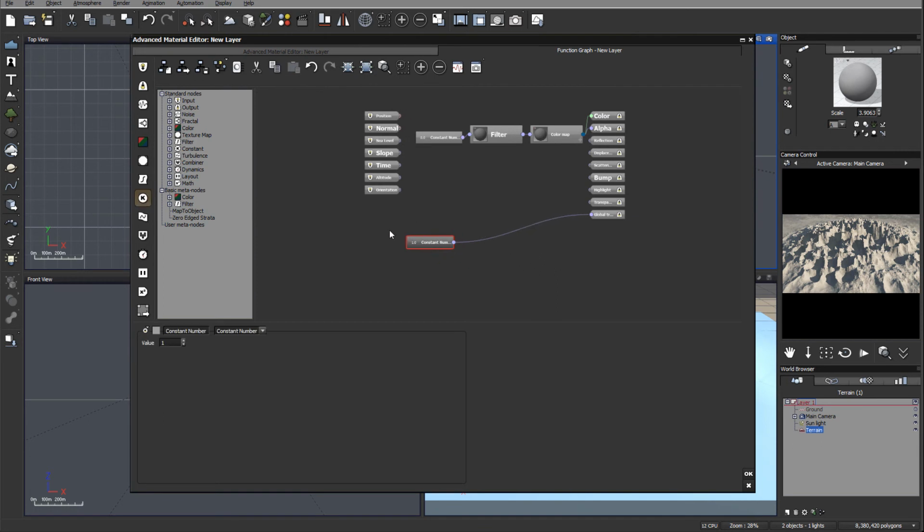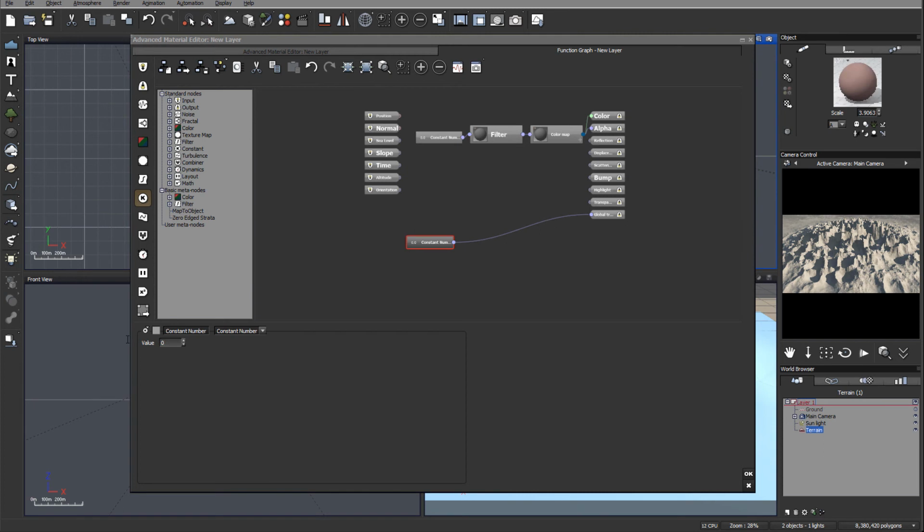Notice right here, when I set this constant, it's connected to our global transparency and its value is 1. So our value is 1. If I set value 0, we'll have it halfway. And if we set the value to -1, then it becomes all the way. So just keep in mind, -1 means there will be no transparency. It's the reason why we're using another area mapper, which allows us from -1 to 1. But again, it will need to be inverted, depending on what I want to do.